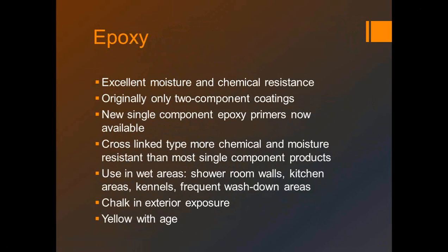Yeah, and depending upon what we want to achieve, again, it's going to really depend whether we use a two-component epoxy or a pre-catalyzed acrylic epoxy, or we have some new versions of a single pack epoxy where you have the part A and the part B in the same bucket, where the part B is encapsulated in solvent, and whenever you roll or spray it to the surface, as that solvent disappears, then it catalyzes on the surface.